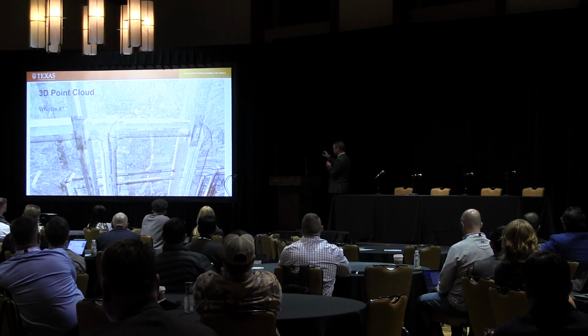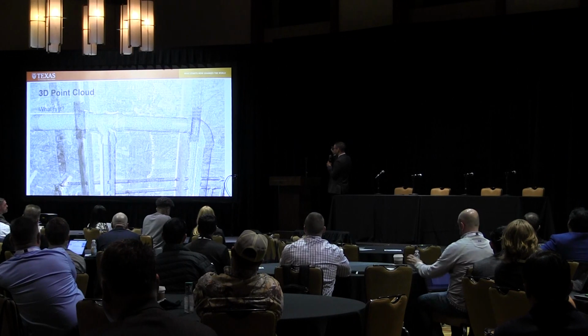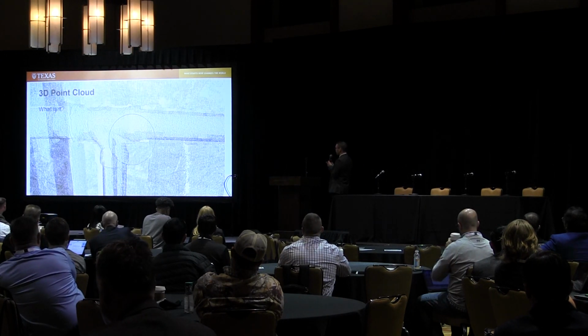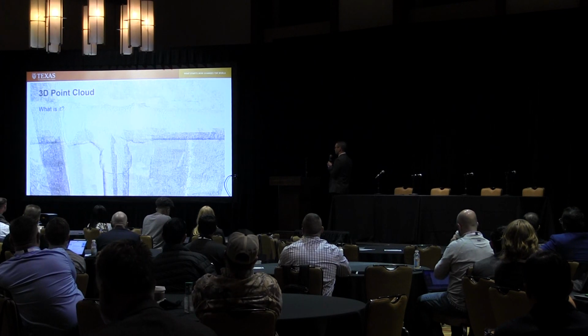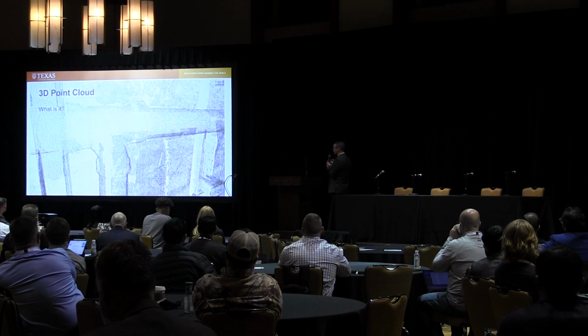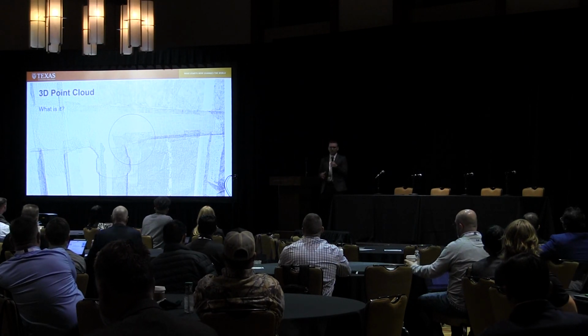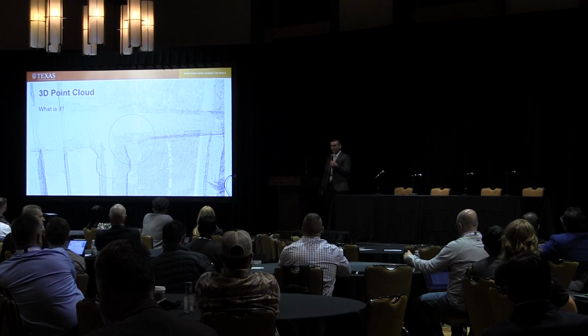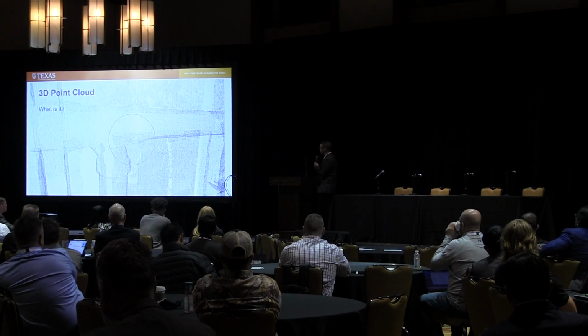And as I zoom in here, you can see what the data is. It's basically a series of 3-dimensional points that give a very accurate representation of the geometry of this wall assembly. And for that simple 15-minute process of capture plus maybe another half an hour to register this together, you'd get a data set that's quite dense, so on the order of 500 million data points. Yes, you heard that correctly, 500 million individual points in this point cloud.